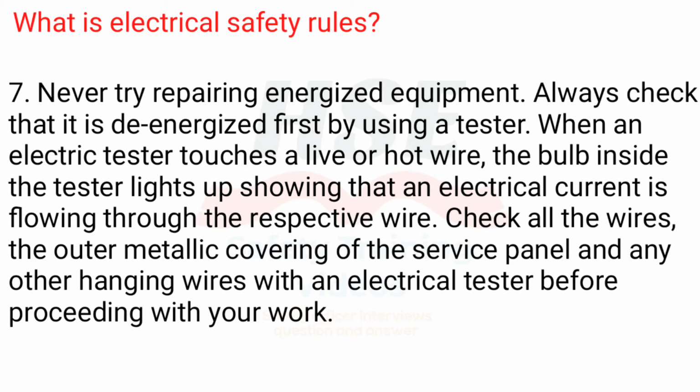7. Never try repairing energized equipment. Always check that it is de-energized first by using a tester. When an electric tester touches a live or hot wire, the bulb inside the tester lights up showing that an electrical current is flowing through the respective wire. Check all the wires, the outer metallic covering of the service panel and any other hanging wires with an electrical tester before proceeding with your work.